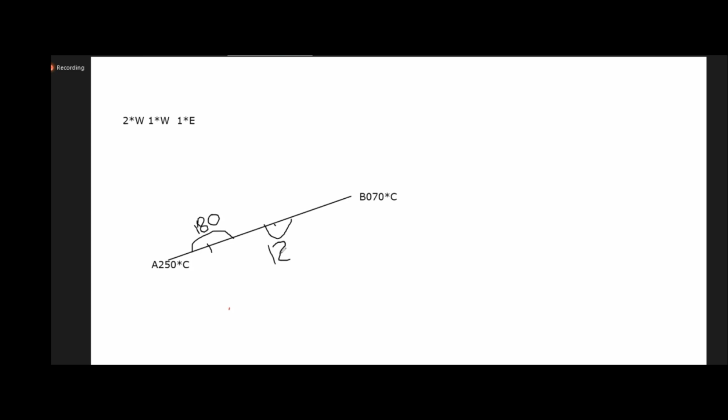Now this position line will be used for different kinds of problems. So for HSA 180, we don't get any position circle, we get a position line. 180 means they are in a reciprocal bearing. Reciprocal bearing means just opposite direction. The vessel is anywhere between A and B. I don't know where we are.